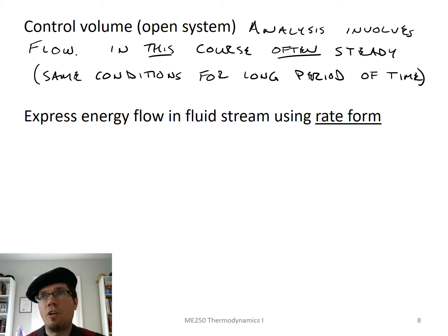And I want to draw your attention, we'll write this down in later lectures, but I want to draw your attention now that there's two different types of steadiness. There's steady flow, which means that your inflow and your outflow don't change with respect to time. And there's steady state, which means your system doesn't change with respect to time. And those are two very different things.